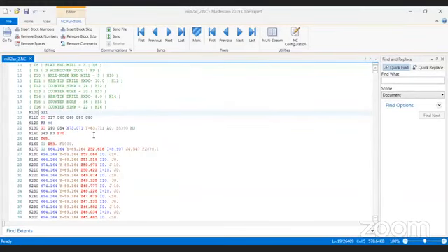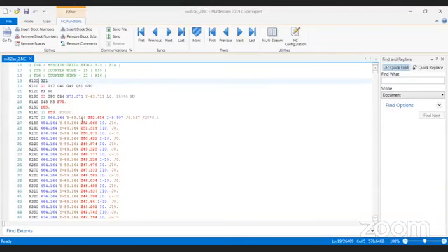So all the toolpaths are now posted in a generic form. If we are having any specific machine, then it will have slightly different codes, according to the controller, which controller you are using, which machine configuration you are having. It will be generating according to those machine details.